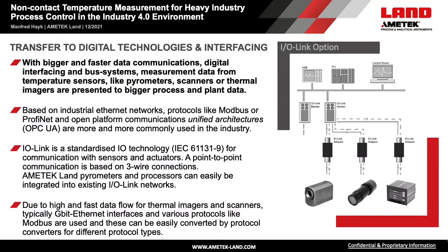Based on industrial Ethernet networks, protocols like Modbus or Profinet, and open platform communications unified architectures, OPC UA, are more and more common in the industry. For example, IO-Link is a standardized I/O technology for communication with sensors and actuators.